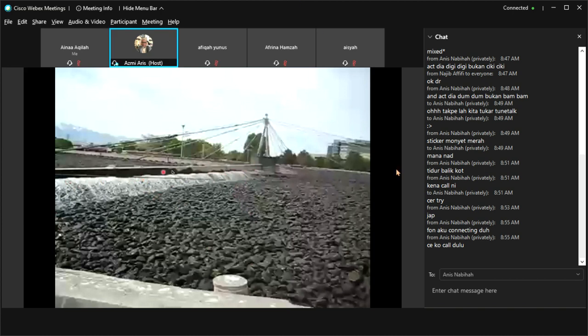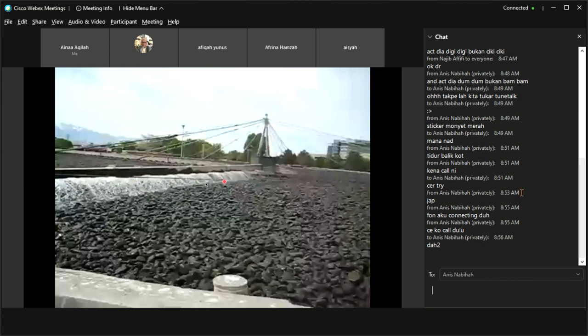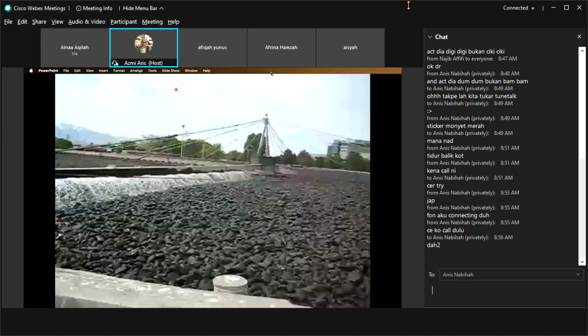If they have uniform distributor holes, then you will have more wastewater coming out here for a very little area, and less wastewater coming out towards the end, which has more area to be filled up. So that's why the distribution of the holes is fewer at the center and more and more towards the end of the distributor. I hope you understand.